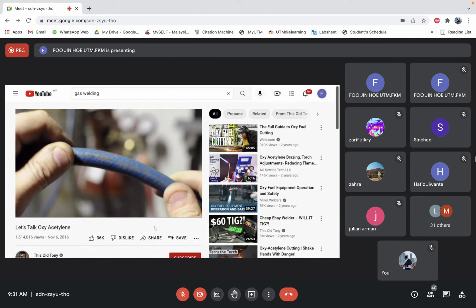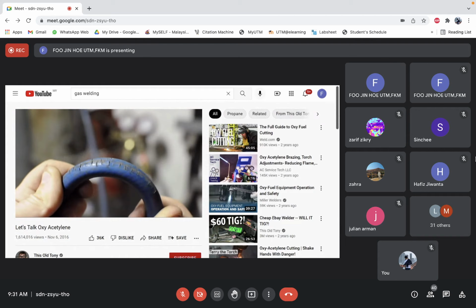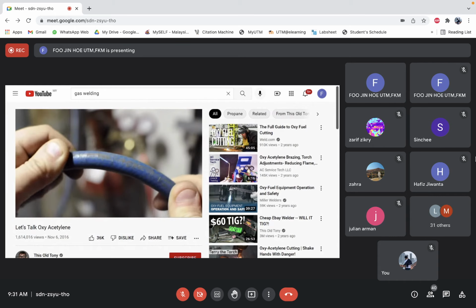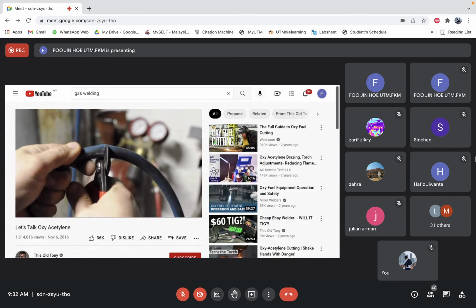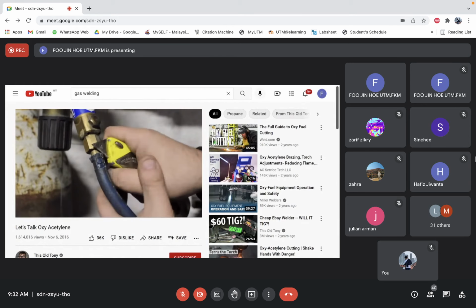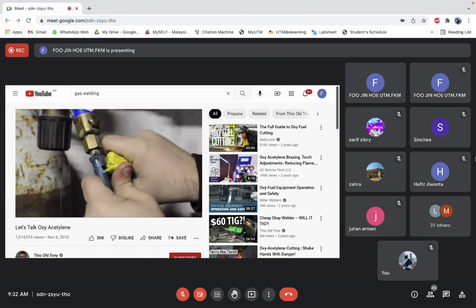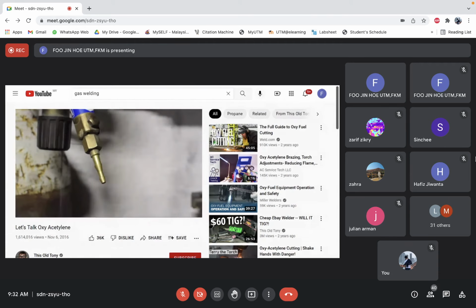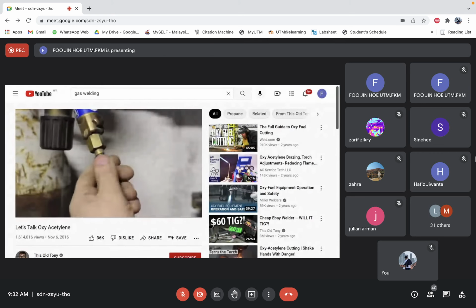I discovered a leak in my Oxy Acetylene lines that I think I just fixed. The Oxy line was pretty bad, but the acetylene also had a small leak that took some soapy water to find. I should probably change these lines out altogether. These aren't that expensive. Maybe $1 or $2 a foot, depending on the size. At any rate, a lot less expensive than blowing yourself up. Maybe a bit more hassle, but definitely less expensive.